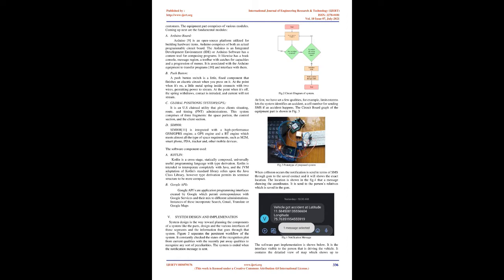The functioning of the system is as follows. Based on the collision, the push button is set off and it triggers the Arduino. It then passes notifications to the GPS, and an SMS is sent utilizing GSM containing coordinates. The display console is additionally used to get messages about the directions, and GSM is utilized to get the location of the vehicle. A DC power supply of 5V is given to the Arduino board. To make this, controls are made utilizing Arduino, while the LCD is utilized to show the messages. Further, the working of this proposed system is as below.